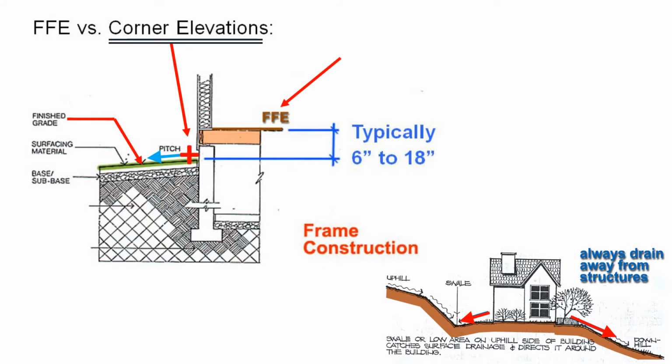But most importantly, if this part of the building, as indicated by the green box here, is made by wood, this distance here, indicated by the purple line, prevents exterior water from easily entering the voids and joints between structures, and also allow the wooden wall and floor to breathe so that they don't decay as easily. Now, why not higher than 18 inches then? First, if you go too high, you'll have more of your building foundations exposed, right? And that is this part, as indicated by the red box here.